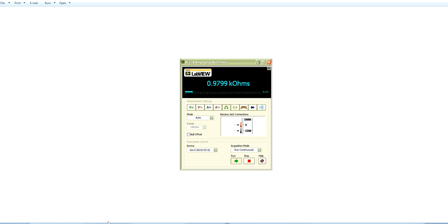Taking our digital multimeter once again, we select ohms, auto, and read the resistance. This resistance is effectively our Thevenin resistance, and it should be comparable to the Thevenin resistance that we calculated in the pre-laboratory. For this particular circuit, it should be 3.9 kiloohms.